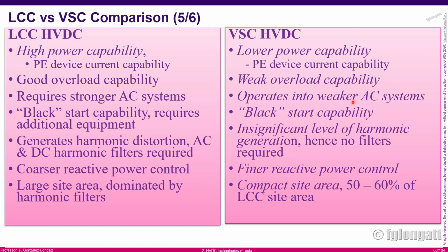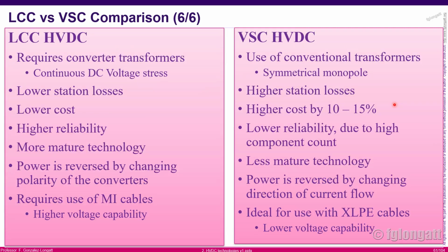They can work in very weak networks. That is good news, and they also have black start capability, okay? The power quality is extremely good. They probably have near zero or null harmonics generation. No filters are required, and they have very fine control of reactive power, okay?